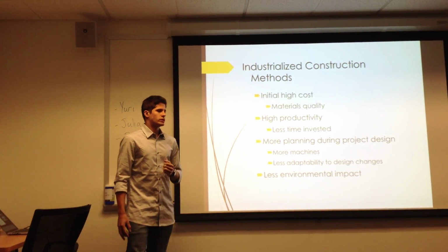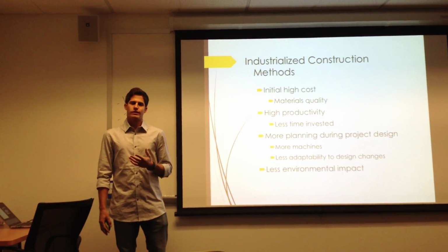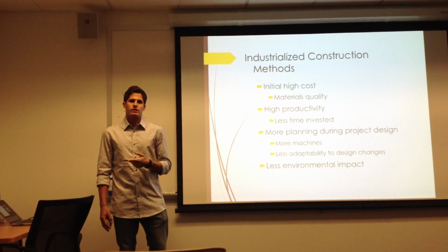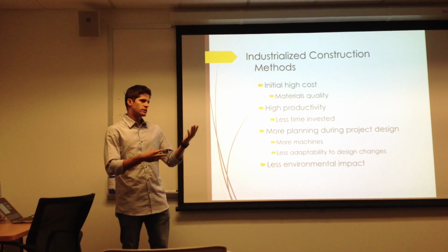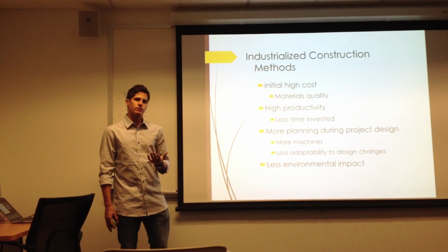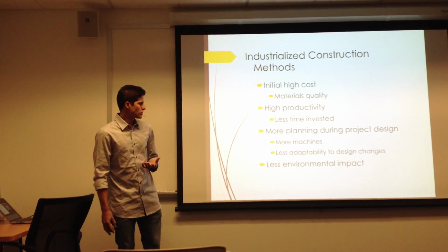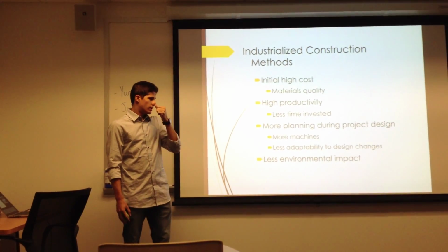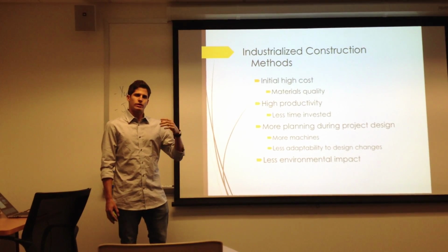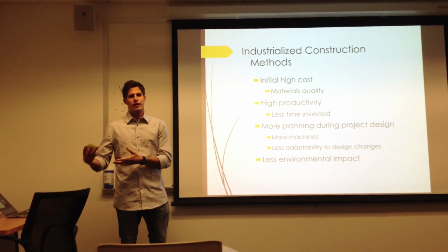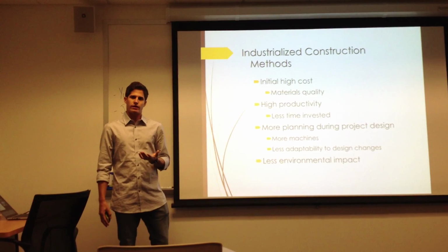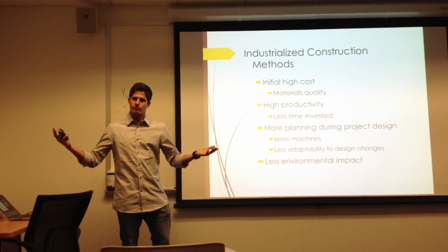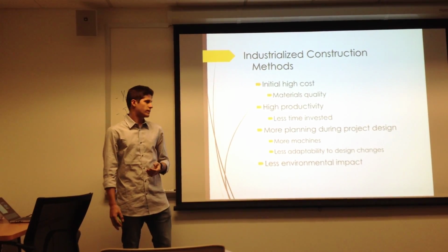It has high productivity because the workers are specialized in doing one or maybe two tasks. So the productivity of the teams increases, and so it's a faster way to build. We also have more planning during the project design. So it takes more machines to transport, handle, and carry the prefabricated elements, because usually they have a bigger size and they're usually very heavy.